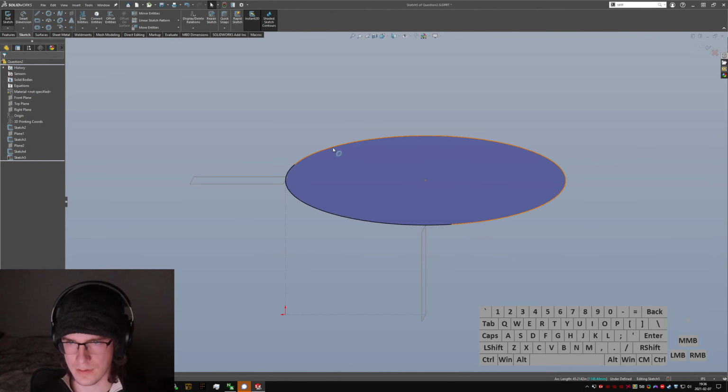you know, I almost want to make another ellipse down there. Maybe I should. Yeah, let's do it. Okay, one more ellipse. Pick that edge, pick that point and that edge, do a pierce.